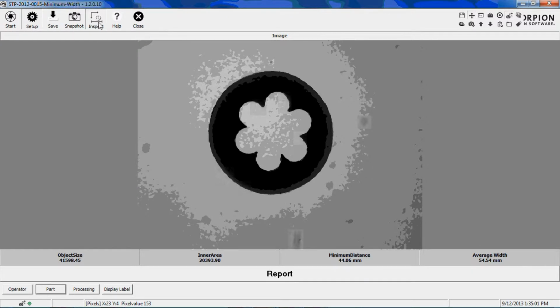Step 2, click Inspect. The moment you click Inspect, boom! It will do all the measurements in one click and show them on the image. You can see all the 6 measurements of thickness are done. And the markings of the thickness points are shown as D1, D2, D3 up to D6. And the minimum thickness is also indicated.